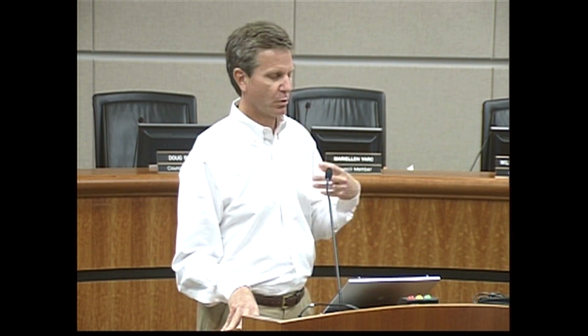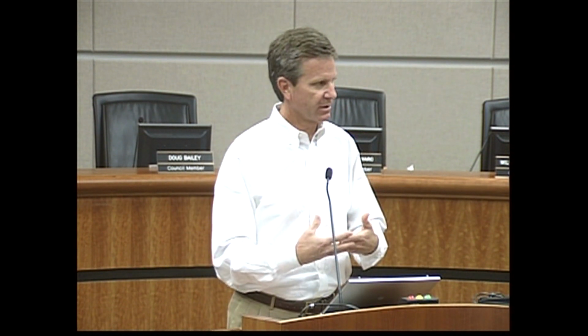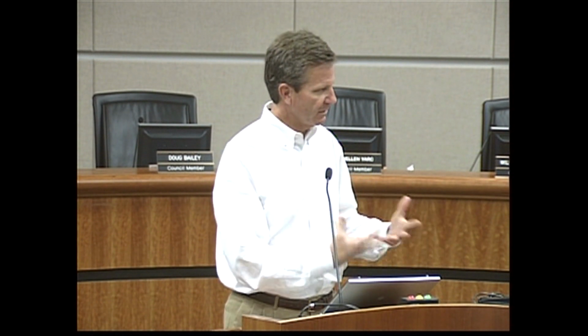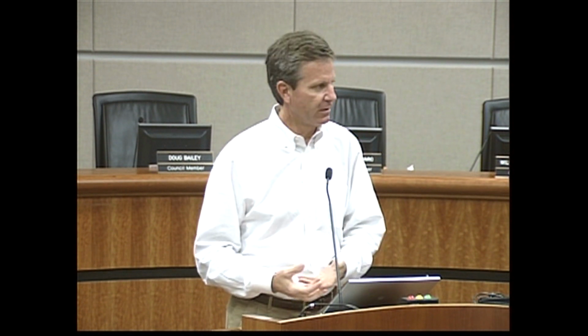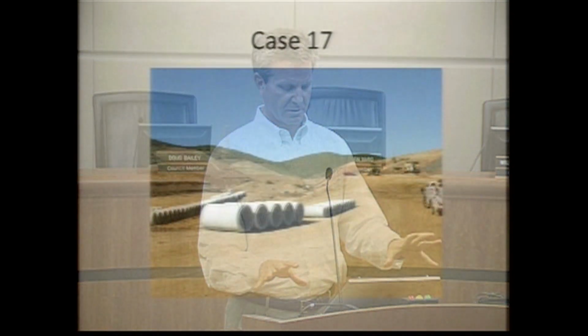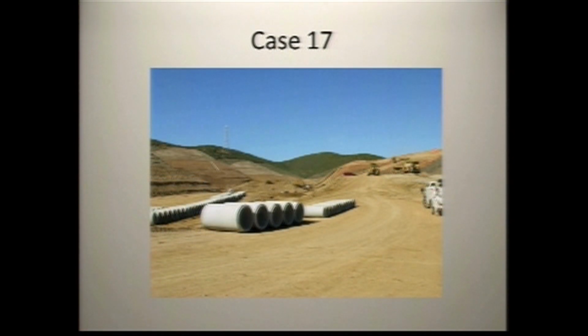If I hit it with Earth Guard, that's actually a coagulant, which sticks particles together, but it's also a flocculant. Once this water all flowed down into the sediment basin that you had created, the Earth Guard is going to make the smaller particles be attracted to each other and stick together, and they get bigger and then they fall out. So it enhances the operation of your sediment basin. So if you just have the basics on a site like this, I know it looks undoable, but if you have the downstream sediment controls and then the basic erosion controls, you're going to meet the requirements of the permit.